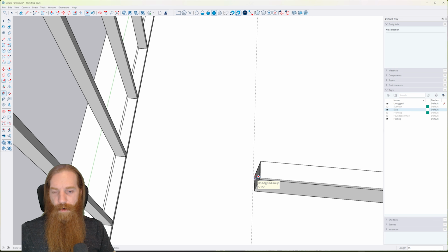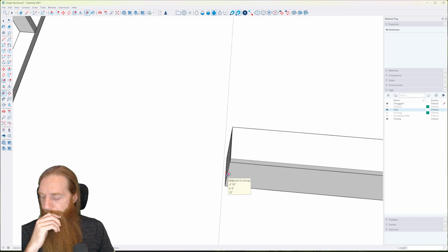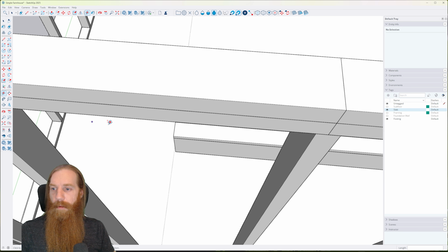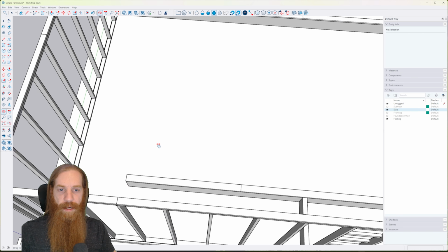It's actually just over, so we could technically bring that out just a little bit more. What is that distance there? Let me see if it's a 1/2 inch. Oh, 1/2 inch for the drywall, that will be on this wall here. So we do need to account for that. So that's perfect. So I did get that all correct when we laid it out the first time. I just wanted to double check. It's been a while since we did that. Wanted to make sure we had that opening correct.